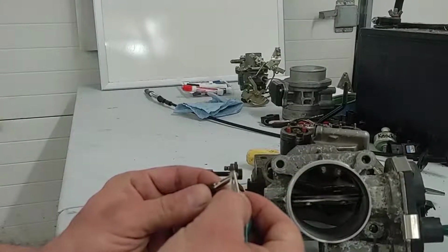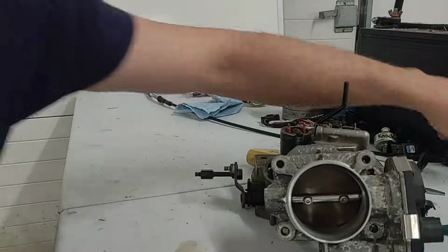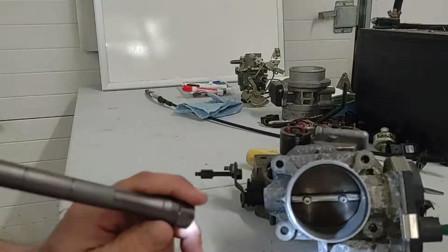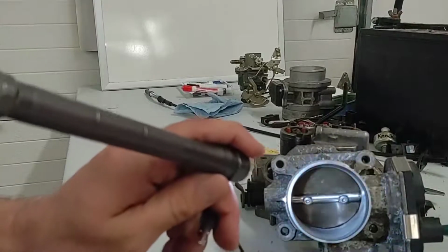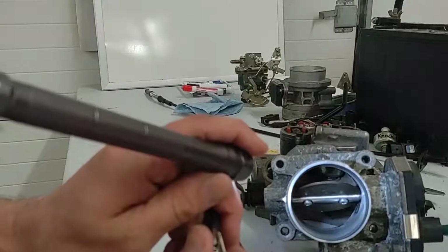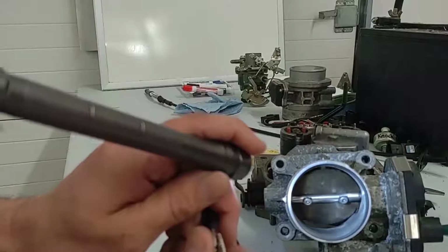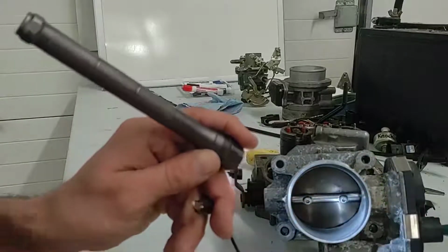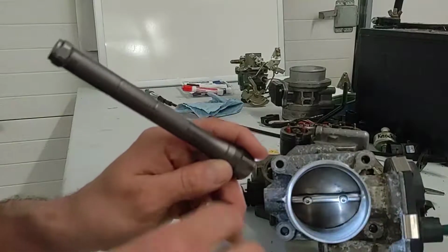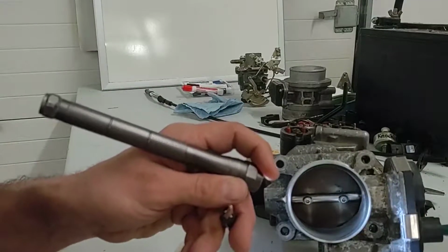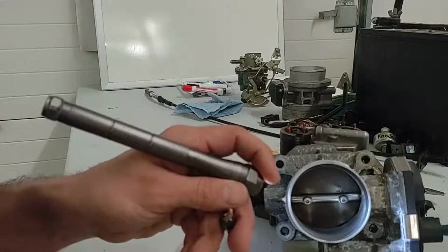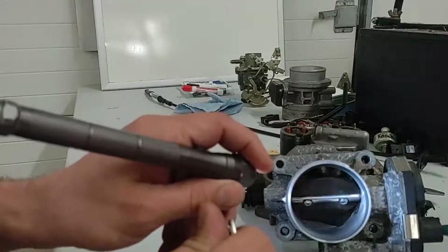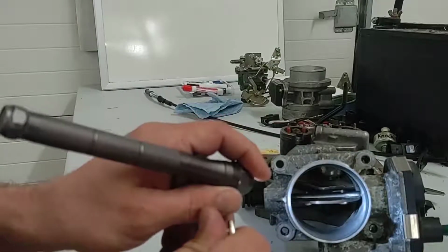see that throttle begin to open, and you might notice it's opening kind of slowly. If I can shine a little bit of light in there, make our view a little better. You notice how slowly it's opening? Remember, I have my power supply set at 2.9 volts. If I increase this voltage a little bit, bring this up to 5 volts. Notice it opens a bit quicker.